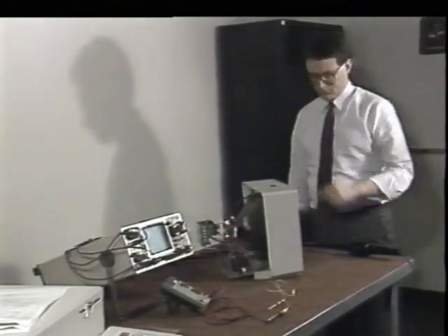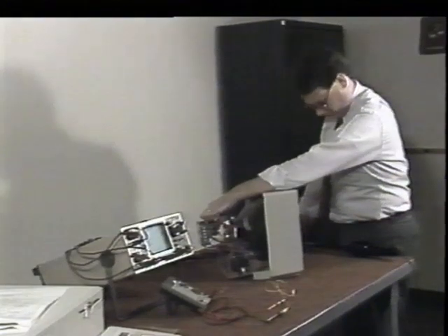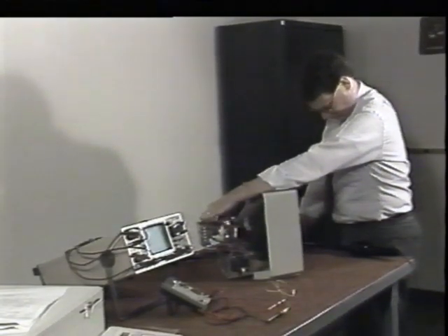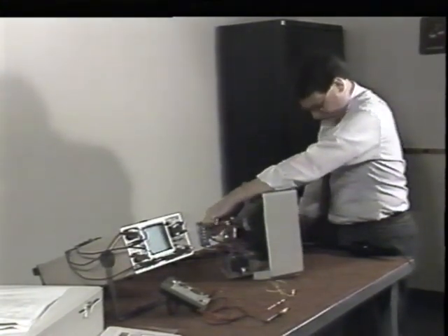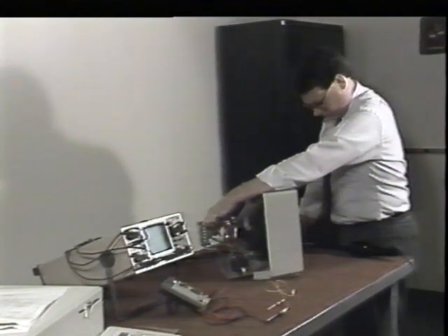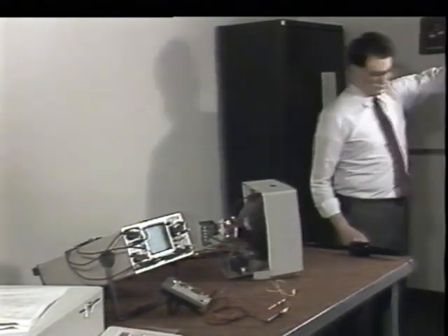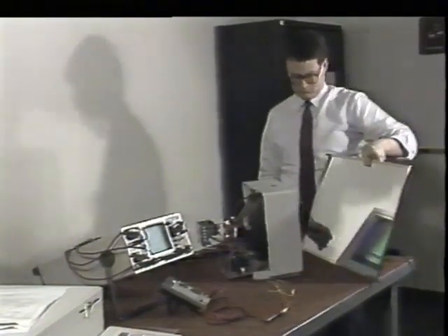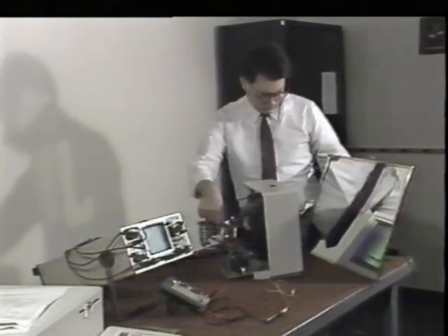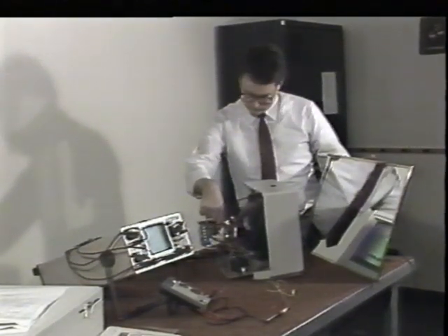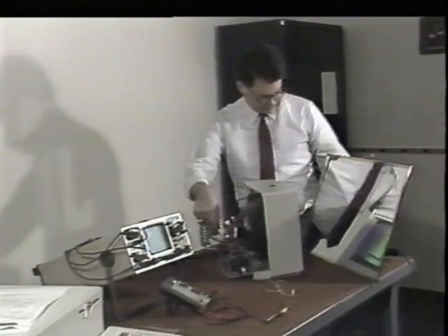You will need to be able to watch the screen and move the magnets at the same time, so you have two choices. One is to stand in front of the monitor and wrap your arms around it to reach the magnets. This is workable if awkward, but be careful not to touch the yoke or other high voltage components. A less acrobatic alternative is to place a mirror in front of the CRT and to stand behind the monitor, observing the screen in the mirror while manipulating the magnets.